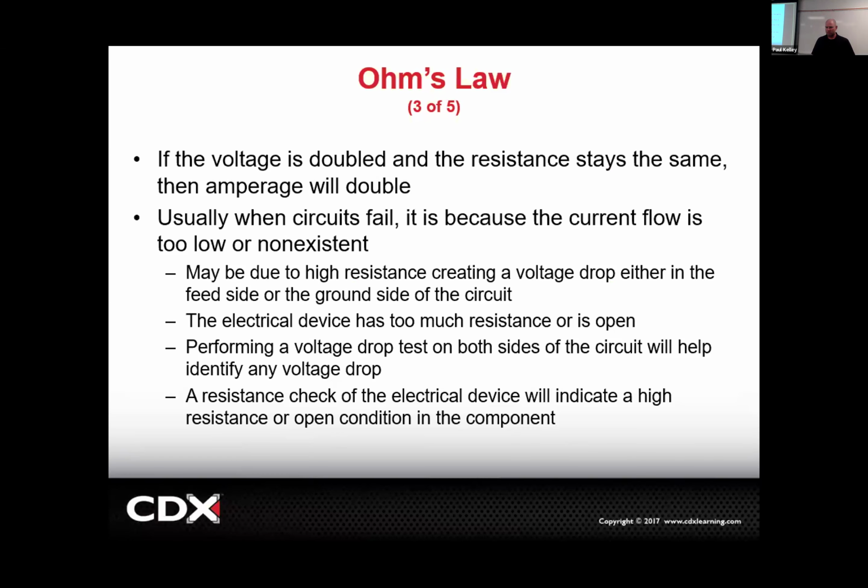The headlight bulb is out completely. If the headlight bulb is not working at all, that's generally going to mean there's excessive resistance, probably a full-blown open, right? If it's an open circuit, the resistance is probably going to be OL, so we just generally call it an open. That's going to have 0 amps. There's going to be no flow.